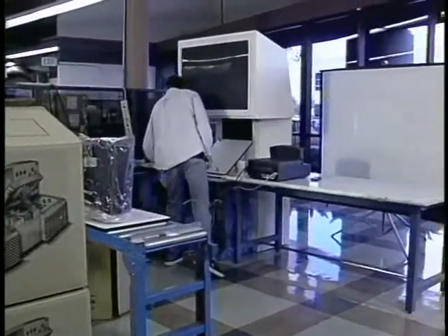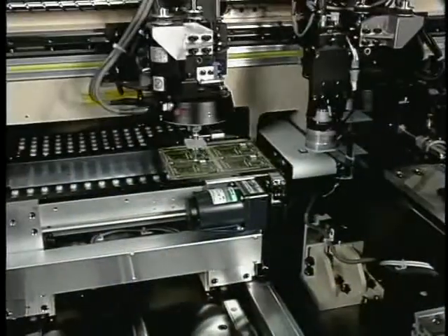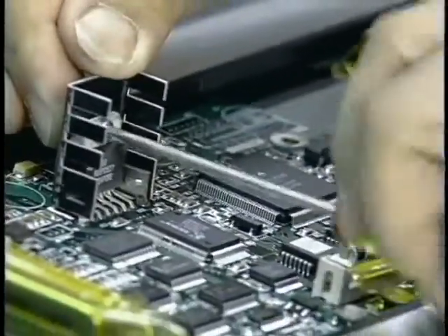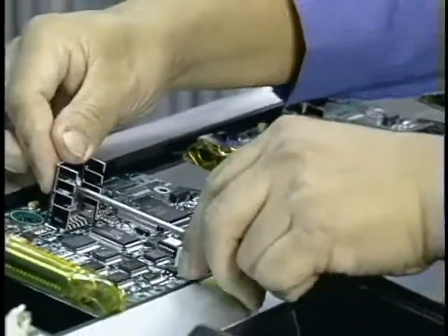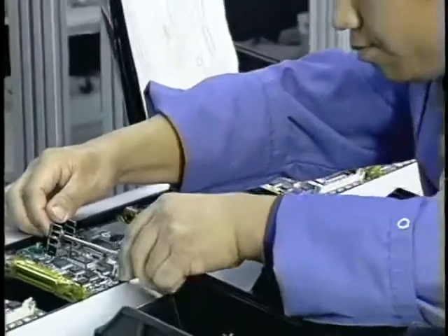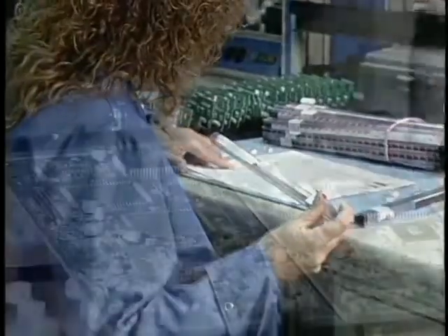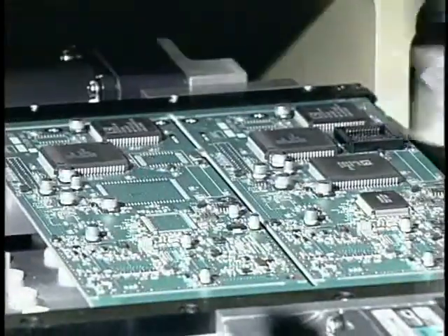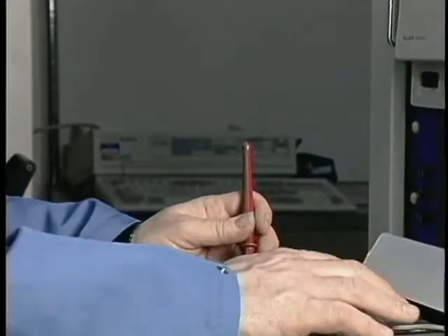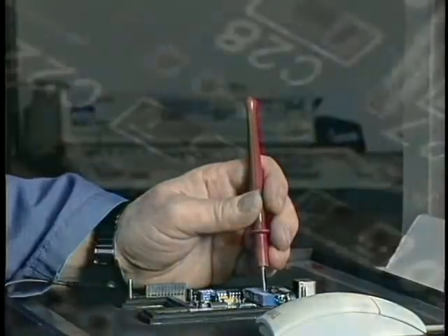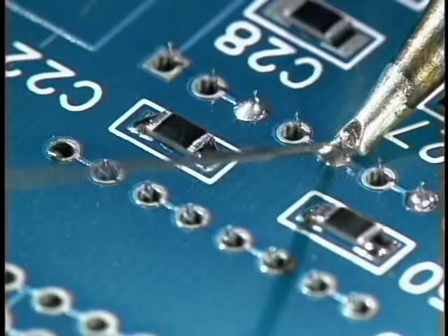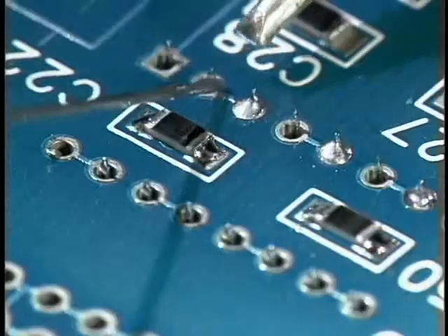For a variety of reasons, there are times when OEMs send out all or some of their electronic design and assembly to EMS providers. These companies are differentiated from OEMs in that they do not produce their own assemblies. They provide services. They purchase the components specified by the OEM, assemble the components into finished circuit boards, and perform post-assembly testing. Usually, any repair or rework required is also done by the EMS provider.